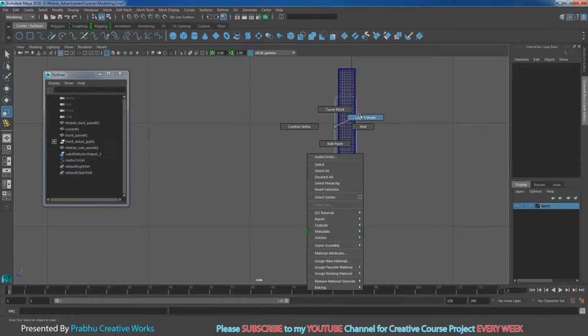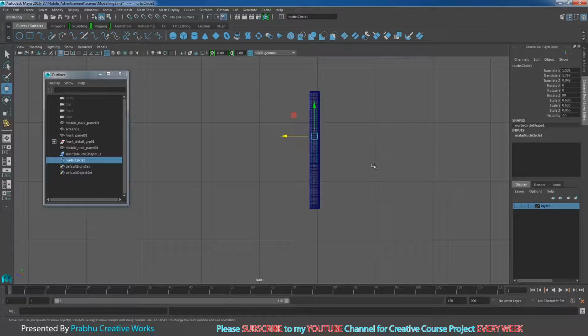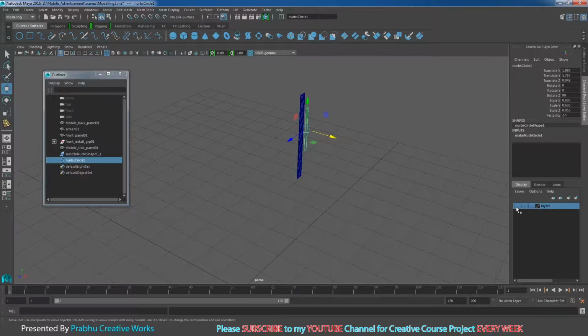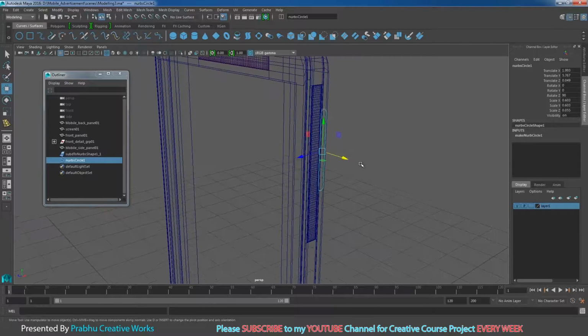Now right click and choose object mode. I will scale in Z and press W. You want to maintain this as a center, press R and scale a little bit in Z. Now this is our volume locker button. I will move a little bit over here. I will unhide this layer to check whether this one is enough or not. I want to scale a little bit in X. So that's it. Now I hide this layer.